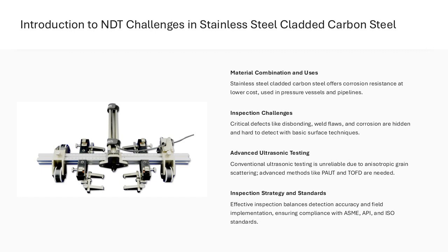This presentation focuses on the most effective and proven non-destructive testing methods for these applications, emphasizing advanced ultrasonic testing, particularly phased array ultrasonic testing, PAUT, and time of flight diffraction, TOFD, supported by complementary surface inspection methods. The goal is to provide an engineering-focused inspection strategy that balances detection capability, accuracy, and practical field implementation for cladded steel components in critical service.